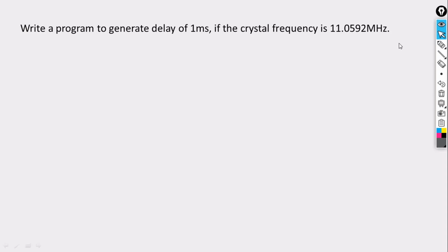clock frequency. First, we take our clock frequency, 11.0592 divided by 12. Again I'll get some 927.2 something kilohertz, I'm writing this as an assumption, which we had seen in our previous slide. So 927 kilohertz, and I'll divide 1 by 927 kilohertz. I'll end up with 1.085 microseconds.